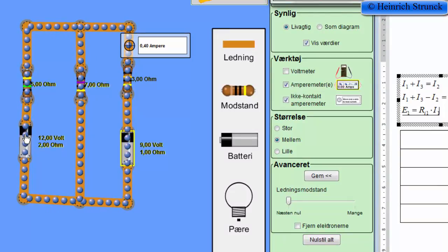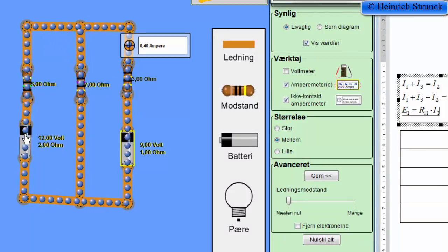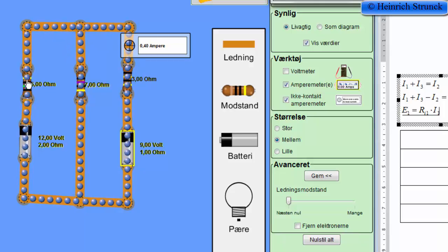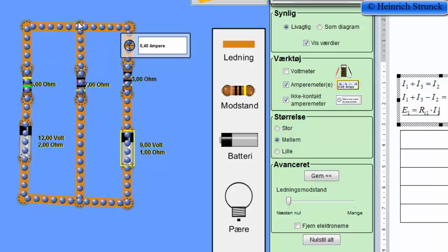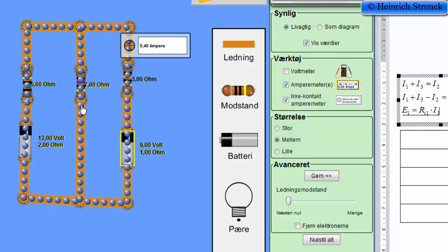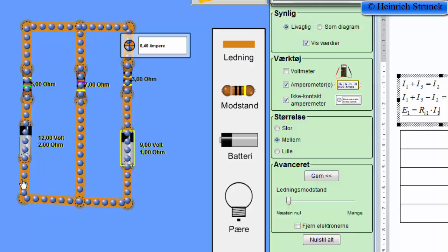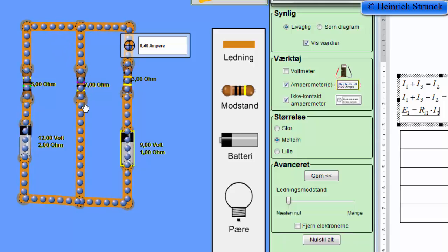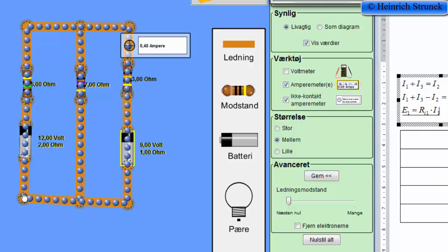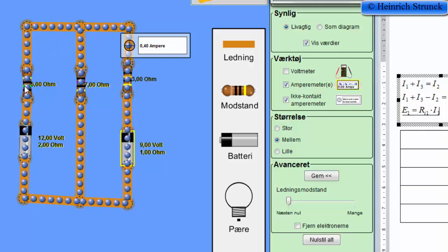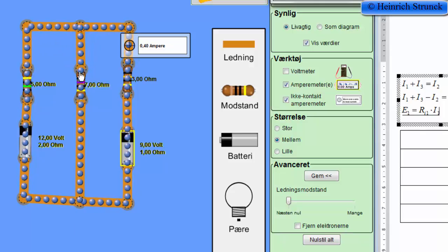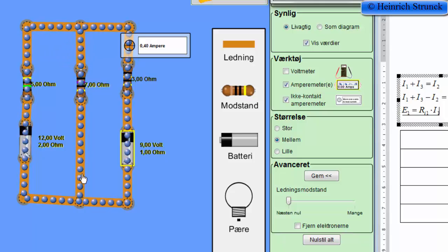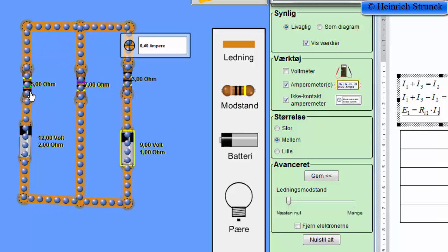On the other side of the equation sign, with all the voltage drops across the resistors, if we go the same way that the current flows, or we guess that the current flows, then the value should be positive. And on the left side, if we go clockwise, we follow the current both over here, I2, and here for I1.